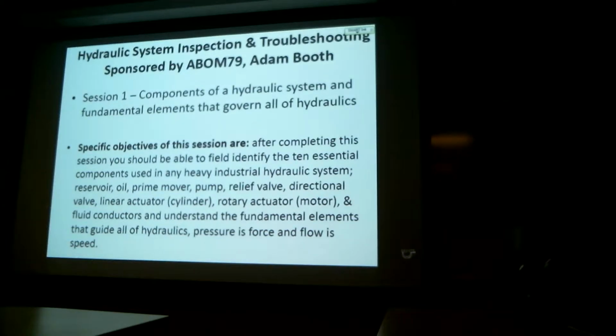What I want you guys to walk away with on this is after completing this session, you should be able to field identify the 10 essential components used in heavy industrial hydraulic systems: reservoir, oil, prime mover, pump, relief valve, directional valve, linear actuator, which is a cylinder, a rotary actuator, which is a motor, and fluid conductors, like your tubes, hoses, fittings, things like that.